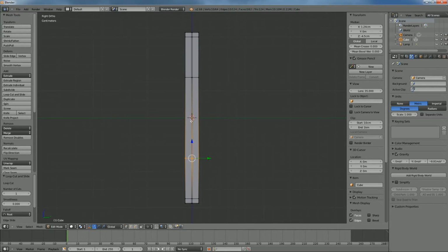And so we'll do the sides now. So we're going to go Control R, and right click. On the Y, we're going to go to 5 millimeters. The Y, we're going to go negative 5 millimeters, sorry. And this side, we're going to go Control R again, right click, and this one's going to go to 5 millimeters. And so this is the area where the finger space is going to be.